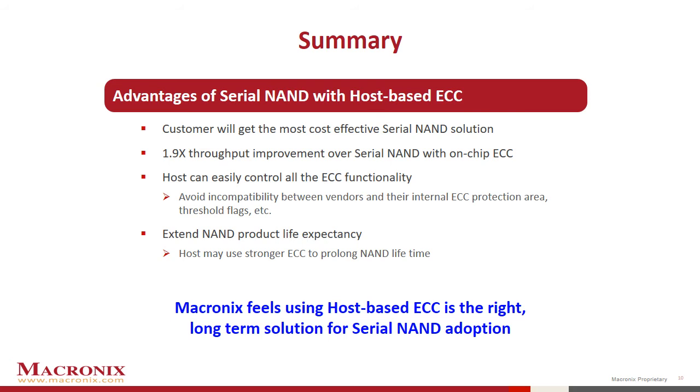There's a huge cost savings moving from serial NOR to serial NAND. However, in this presentation, I discussed the added cost savings from removing the on-chip ECC from the NAND die. The cost savings will more than offset the minor cost increase in the host IC.